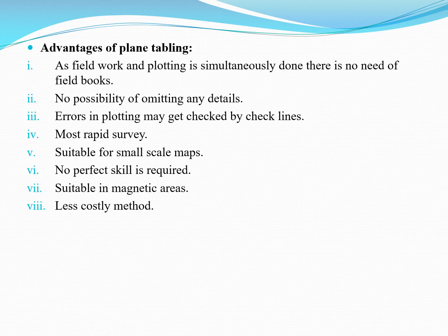Next point is advantages of plane tabling. As the field work and plotting are simultaneously done, there is no need of field books. This is the first advantage of plane table survey. Next is no possibility of omitting any details, means there are no chances of omitting any details.